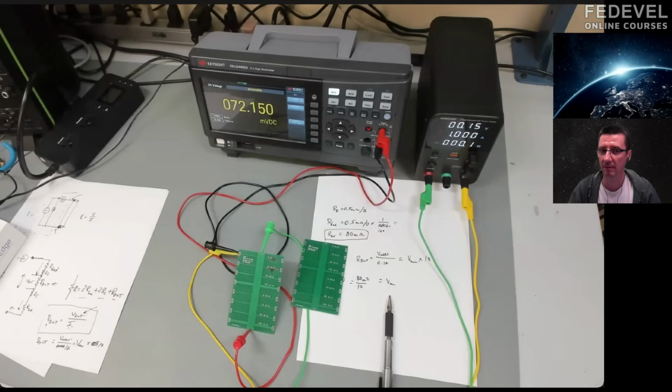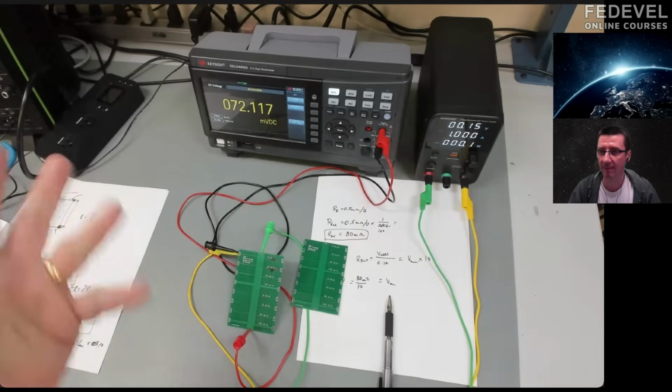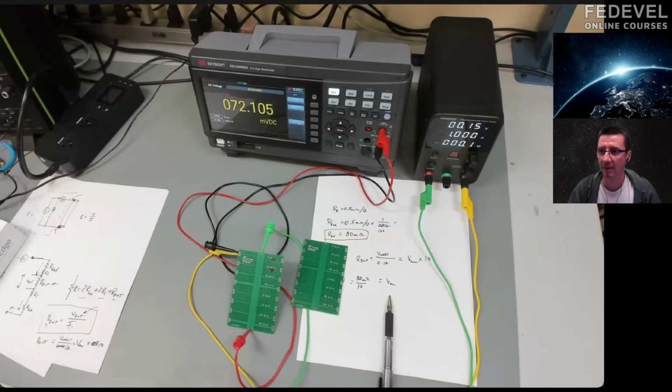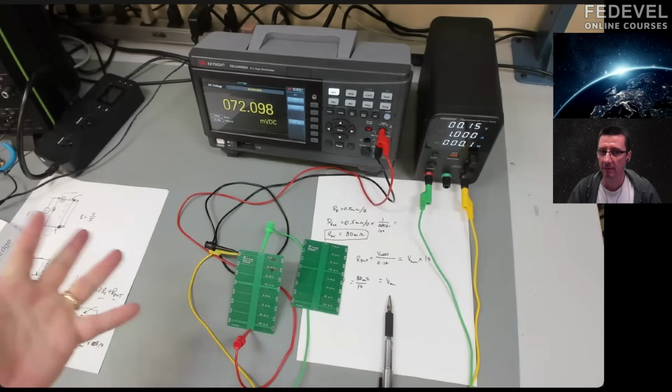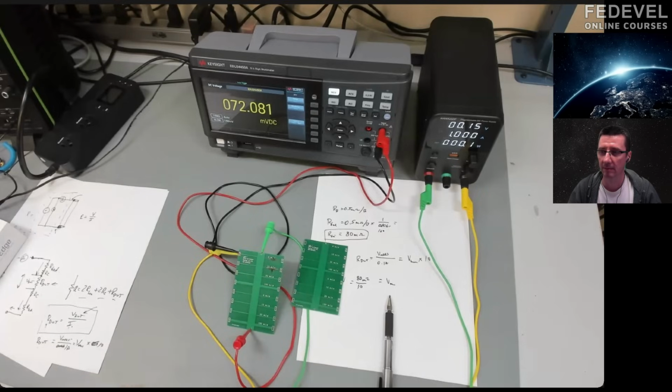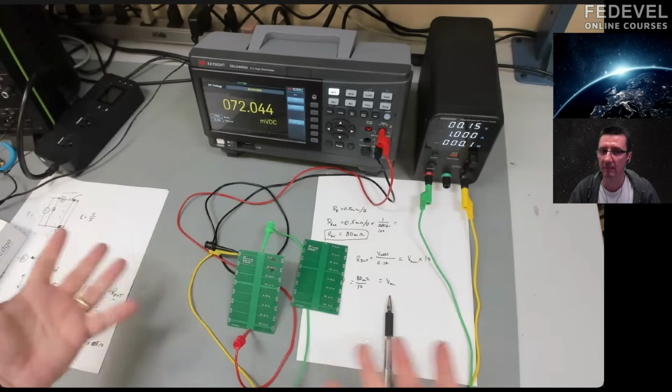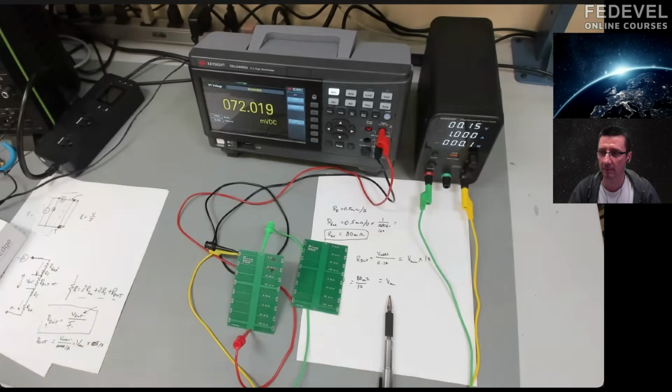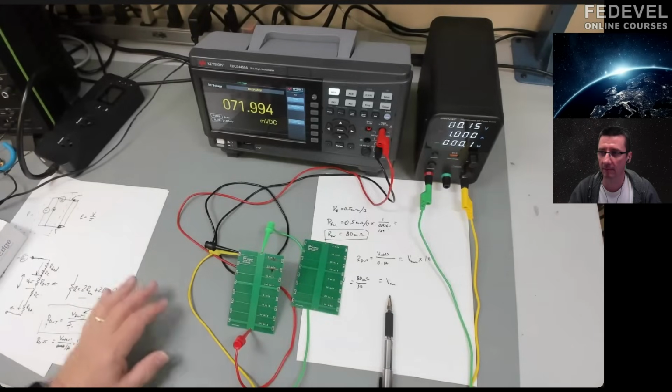Right. And not only that, but I use the Saturn PCB tool a lot because it's really simple and easy to use. It has the IPC spec in there to estimate. It depends on the temperature rise that you care about. It depends on the thermal environment of the trace. And so it's only meant as a rough guideline. And there's a lot of margin built into it.